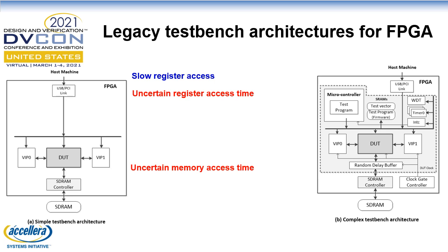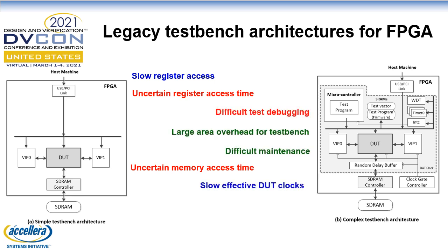The alternative, complex testbench architecture can resolve these problems by embedding a microcontroller and hiding DRAM latencies by implementing a clock gating scheme in the synthesizable testbench. However, it incurs other difficulties and costs.